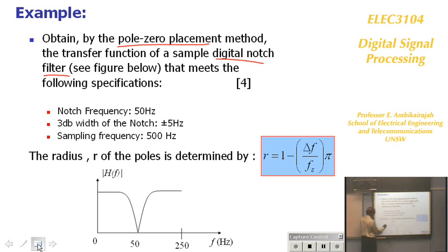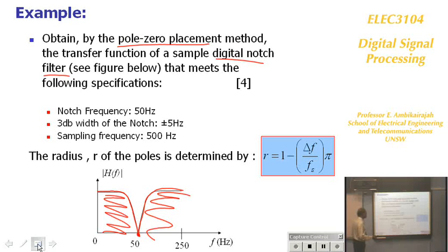So in this case, here is the filter. And this frequency in hertz should be taken out. But the filter should be flat like that. Take out that frequency and then it goes back. So all these frequencies are passed. These are all passed. That's taken out. That's called a notch filter.